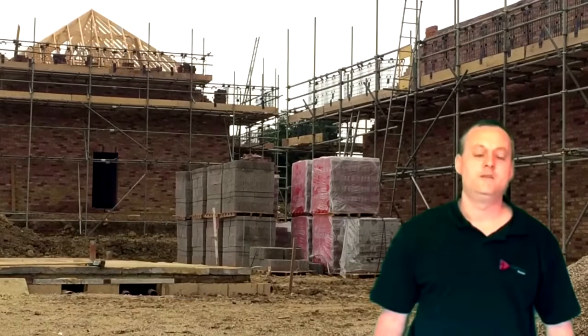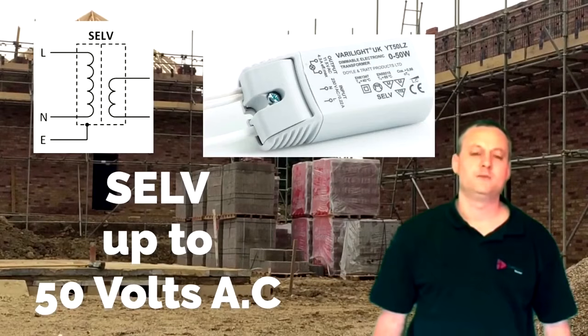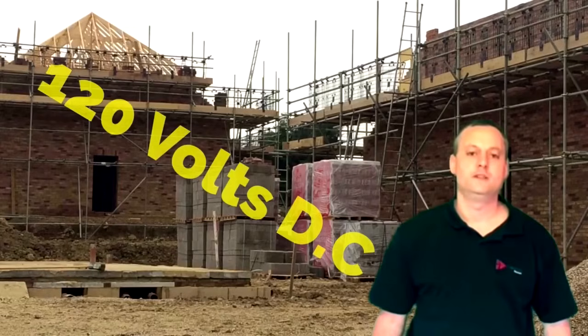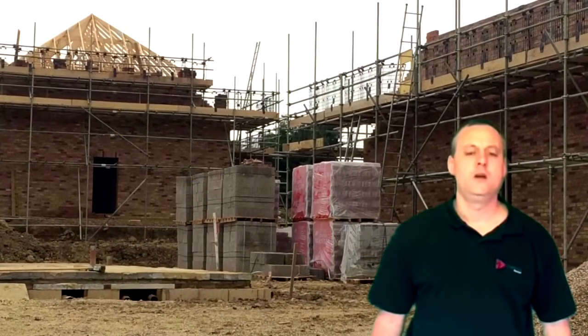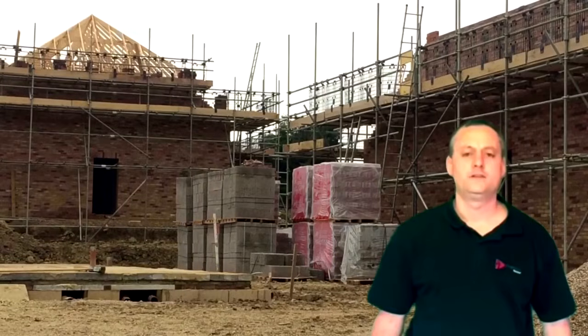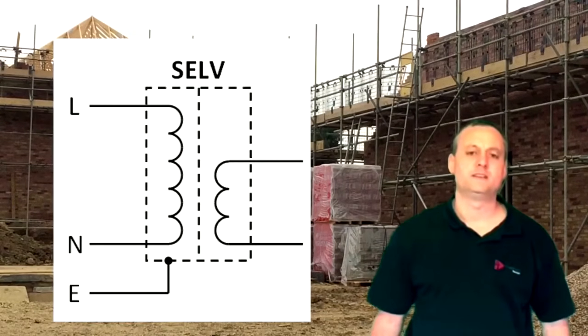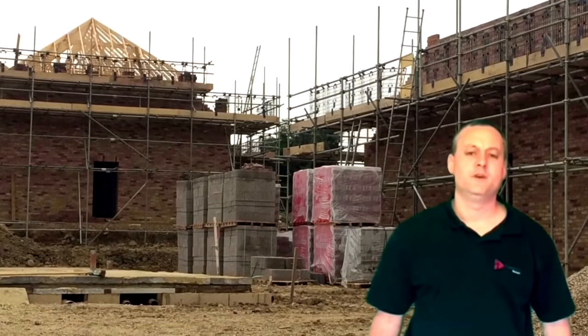We mentioned in this section SELV, separated extra low voltage. And we said this voltage range AC was up to a maximum of 50 volts, or up to in DC a maximum of 120 volts. We looked at how an SELV transformer has no outgoing connection to earth and therefore is electrically separated, which is a method of protecting against electric shock, as well as the voltage being no greater than 50 volts AC as well.